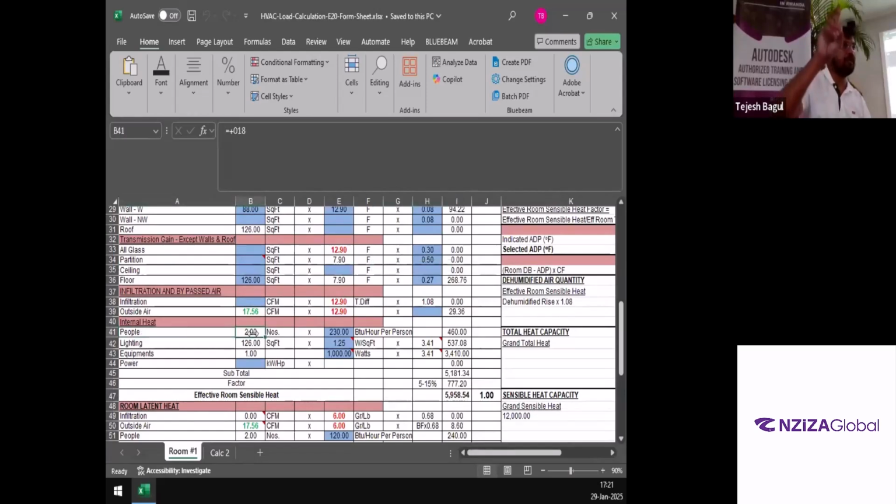We had two people, patient and their guest. Most of the time, you can also consider the patient because the guest is intermittently over there. As we can remember from the first day, we had patient rooms, and they are the ones that are exposed to the indoor climatic conditions again and again, right? So that's why, to make sure we have our equipment adequately sized, we will take two people. And this is the BTU per person.